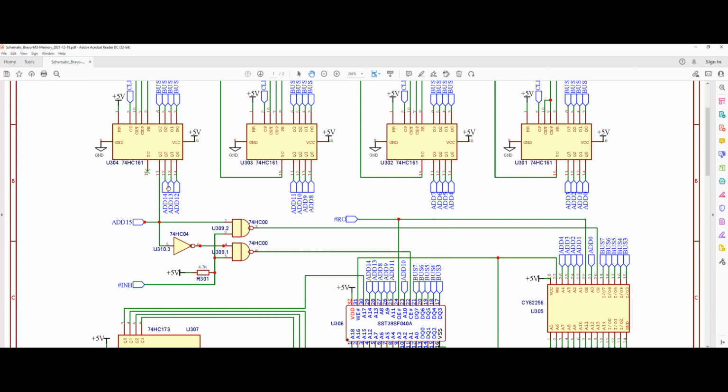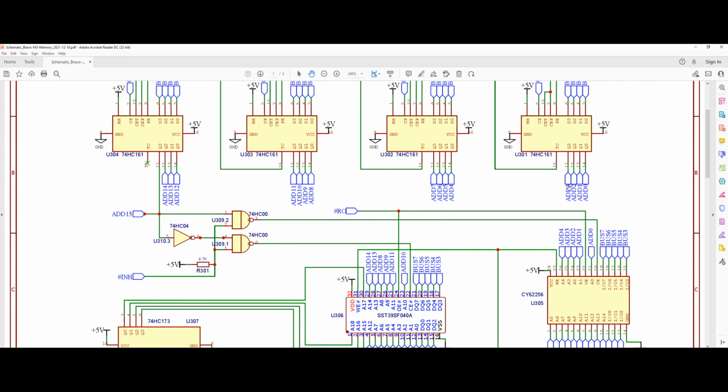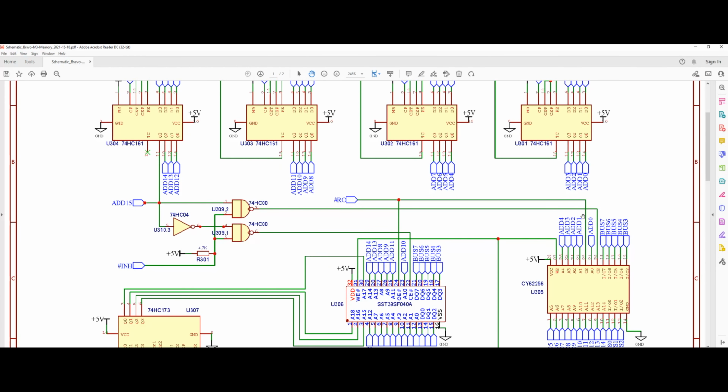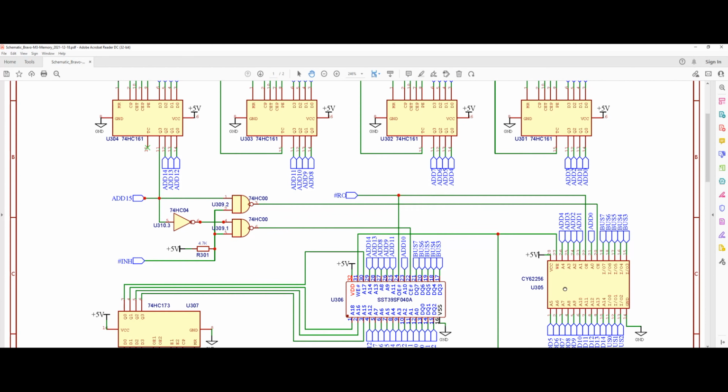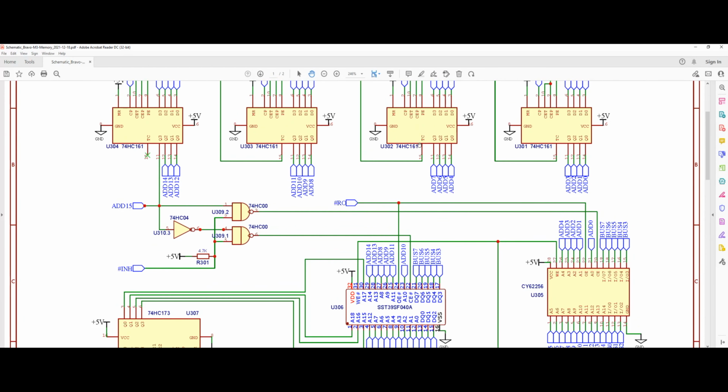We actually have one of those pins which plays the role of enable/disable. Therefore, we are only left with 15 pins or 15 bits here. And those 15 bits could only address up to 32K, whether it's our RAM or our flash memory. It doesn't matter. It only could address up to 32K, right? Now, our RAM is a 32K RAM, so we have no problem there. Everything is connected to our address line, and we basically could address all that 32K using our 15-bit output.